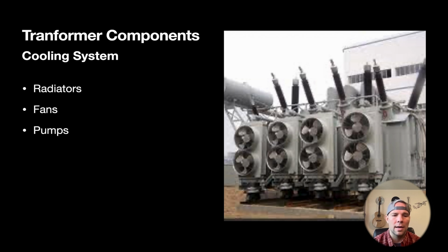And then you also might have cooling water that's run through the transformer through separate tubes, separated from the oil itself. They're not just filling it with water, but they have water tubes running around the core of the transformer internally. The highly cooled water absorbs the heat, goes back out, gets cooled down again, and is pumped back through.